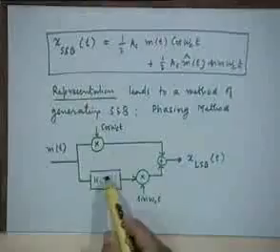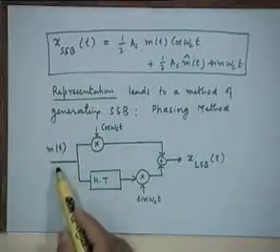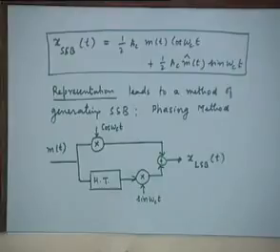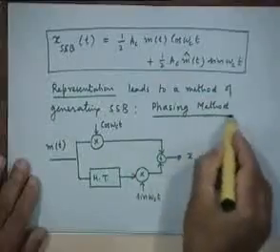However, since the whole operation has to be done around baseband, this Hilbert transform is operating on the baseband signal. It's much easier to approximate such a Hilbert transformer than to realize the high Q tuned filter that is required for SSB filtering. Both the methods are used in practice, this one as well as the sideband filtering method, right? Both have their pros and cons, but this gives you an alternative. So this is a second way of generating the SSB waveform, which is called the phasing method.